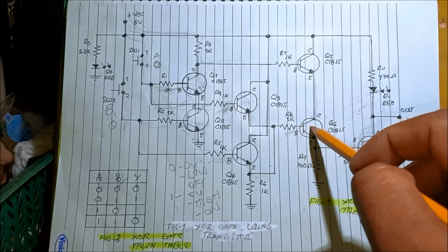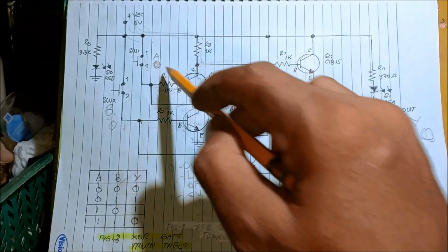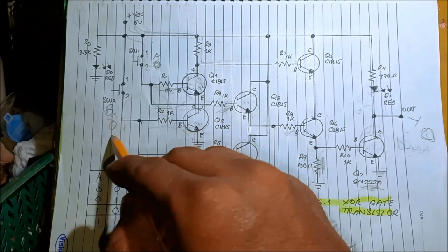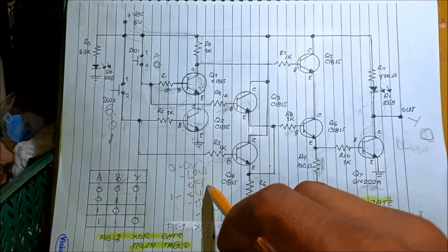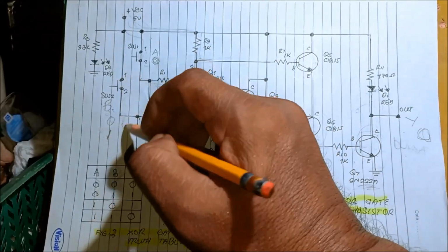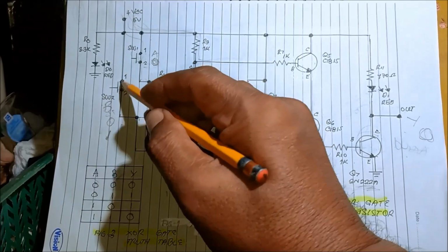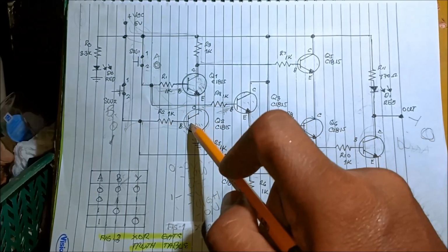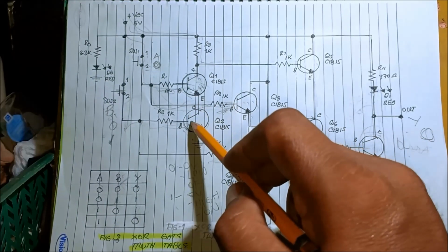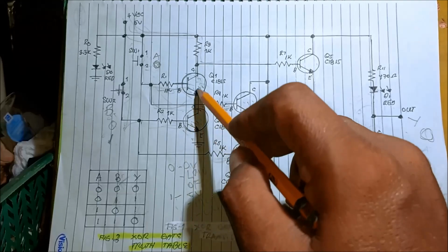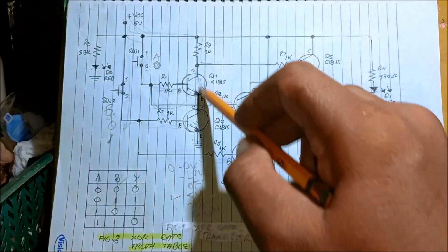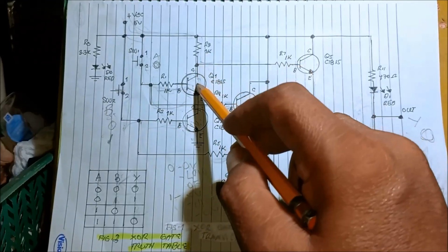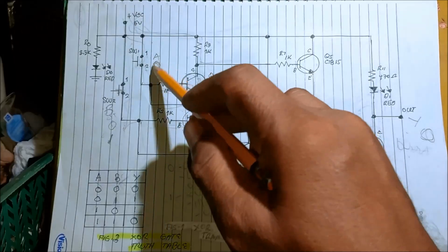Okay, there's no base current here when they're pressing the switch 1. And the switch now for B is 1, which means it is on. When it is on, logic 1 means the switch is closed. When this is closed, current flows into this transistor, making this what? Still off, because there's no current for collector to emitter, because this transistor is off, still 0.